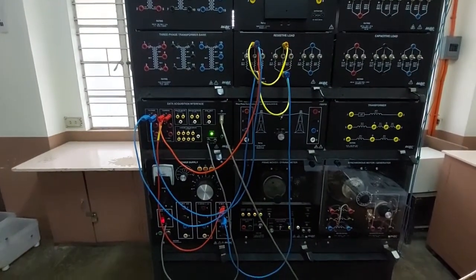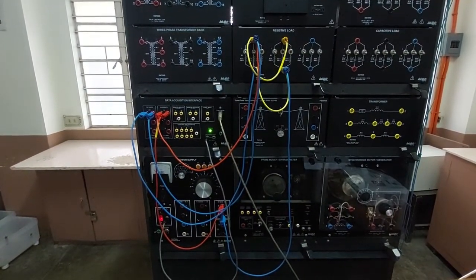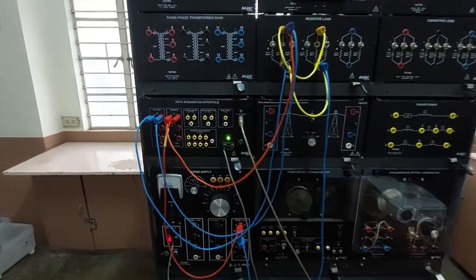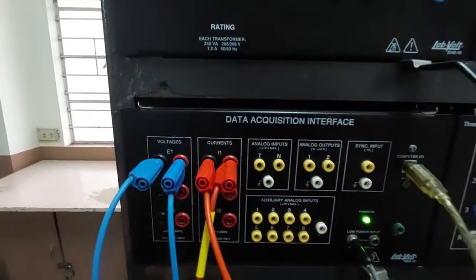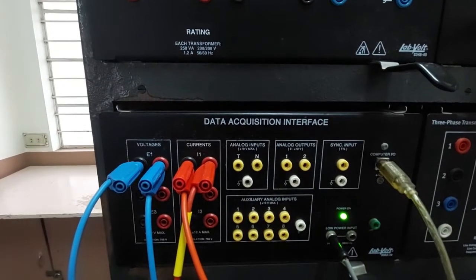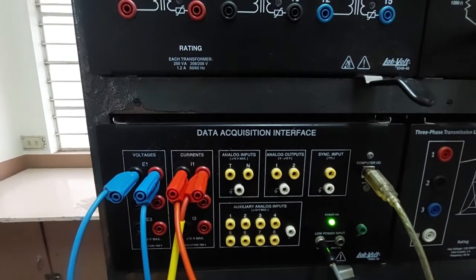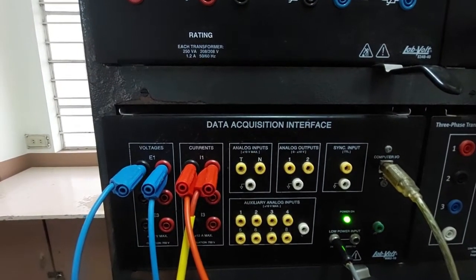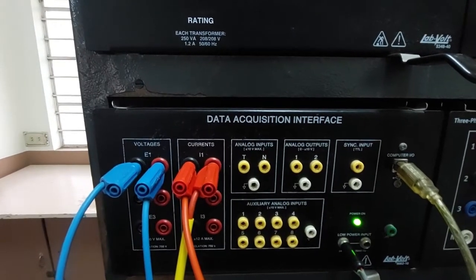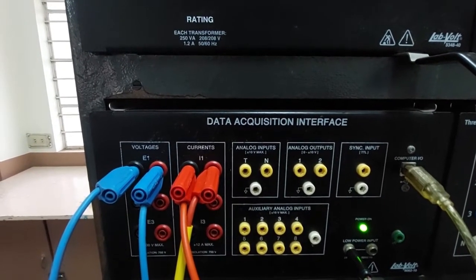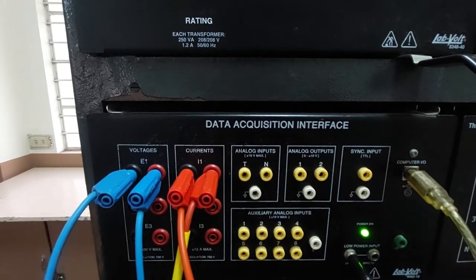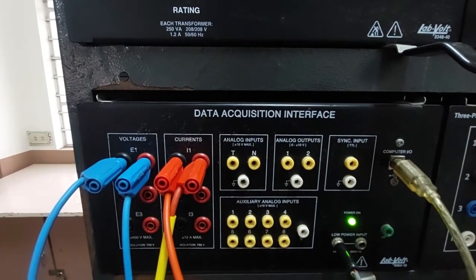And then after connecting that one, we will connect the 120 volts into our ammeter. Take note that our ammeter is always in series with the load. So therefore, in this data acquisition interface, the ammeter is also protected by a fuse. So that is the protection for this lab volt.